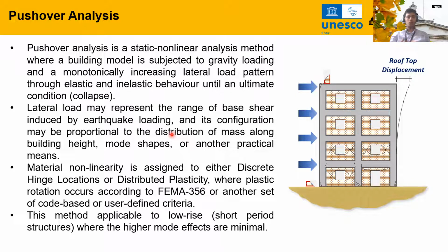As I said already, the material nonlinearity is assigned into the numerical model by using either discrete hinge locations or distributed plasticity. FEMA 356, for example, gives criteria for modeling these structures, reinforced concrete or masonry structures. And a very important point here: this method of nonlinear pushover analysis is applicable only to low-rise buildings, these short period structures where the higher mode effects are minimal, and these buildings mostly behave in the first mode displacement profile.